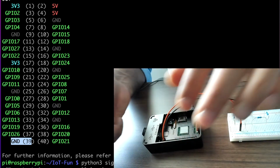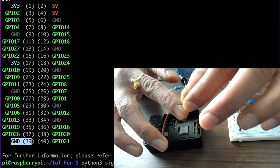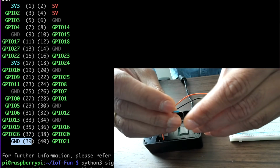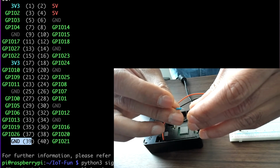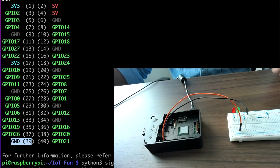Okay, so don't supply a direct current. Always use a resistor. One end of the resistor will be connected to the GPIO pin. The other end of the resistor will be connected to the anode of your LED, and that's how you're going to make the connection. LED and GPIO together, resistor together. One end will go to ground, one end will go to positive voltage. All right, so many of you already know that, so sorry if I am rat holing on this, but if you are not aware, this is how you need to connect.